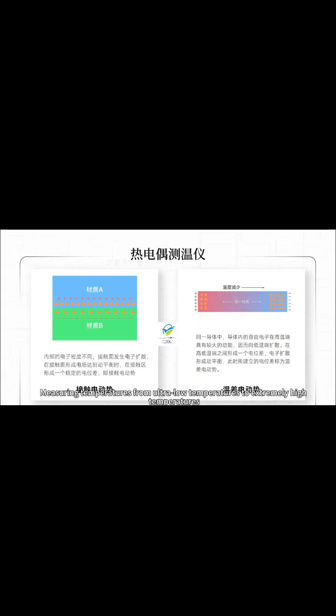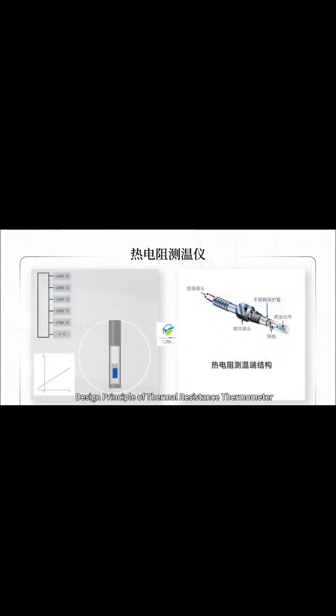A bimetal thermometer is a thermometer that works by using the difference in expansion of different materials, and bimetal can be seen on many components that control temperature. It is made of pressing two pieces of metal with a large difference in thermal expansion coefficient together, and when the bimetal sheet is heated, the metal sheet bends to the side with a small expansion coefficient because the tightly combined sheets cannot separate into layers. Depending on the temperature, the curvature also changes.